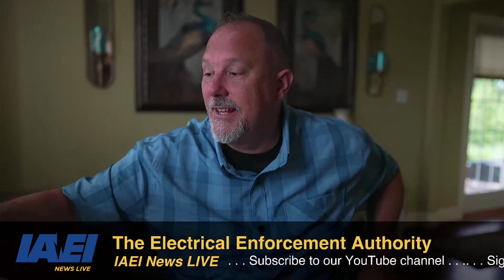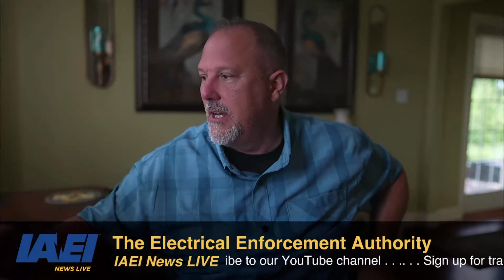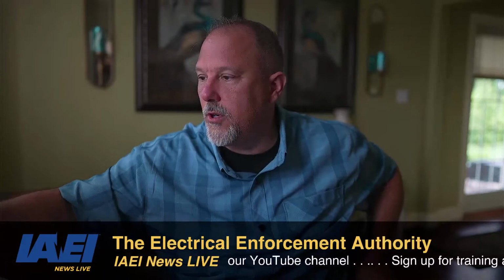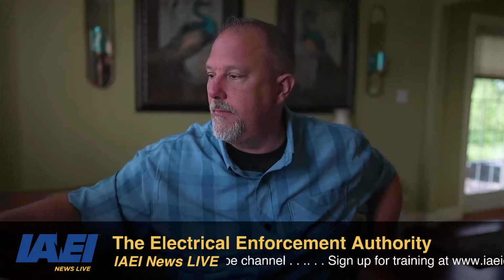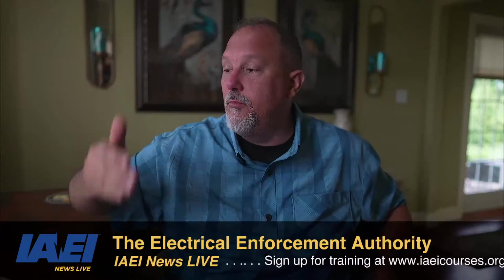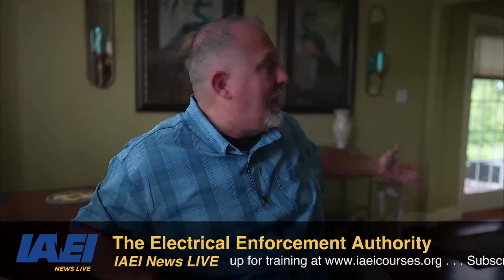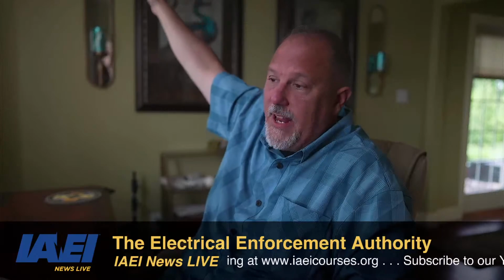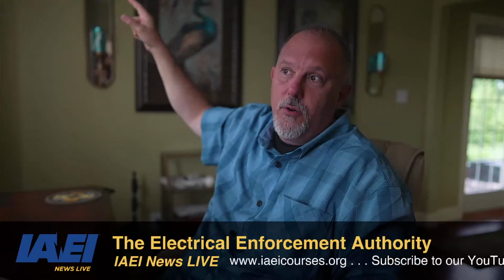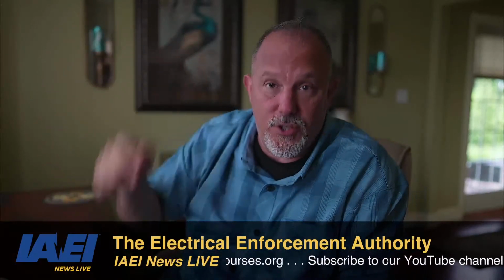Anyway, let's get back to 210.52. This is what I love about the language. All right, so 210.52, we're talking about receptacles located within cabinets or cupboards, or located more than 5.5 feet above the floor. So if in this room I had a receptacle up higher than 5.5 feet, that receptacle would not count as one of the required receptacles in 210.52.